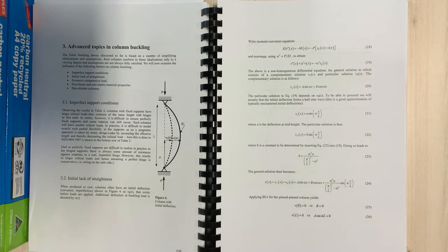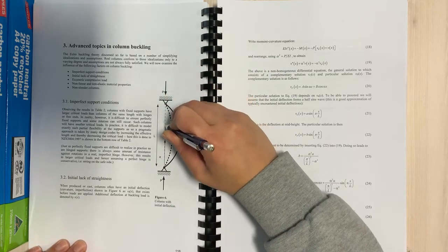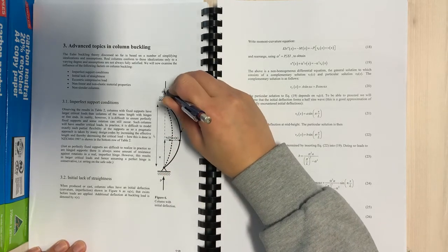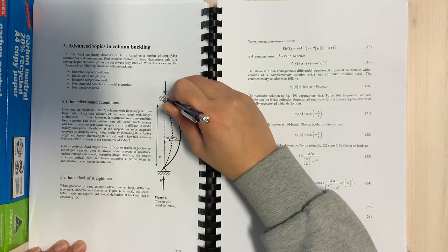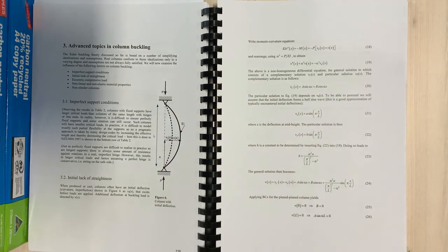And we're assuming that the load is being applied exactly, directly, concentrically, right through the centroid of the section. So everything has been very idealized up to now. Idealizations are fine. They can be useful, but once you have an idealization, you now want to turn this into a design model. So you want to be able to use this theory that we've developed of P Euler to relate that to how we can actually design a column in a real building.